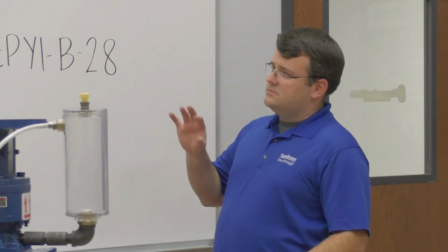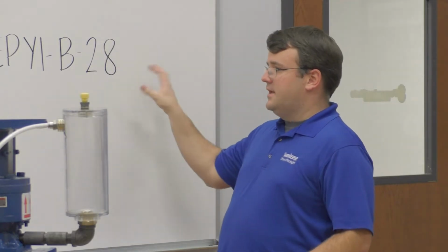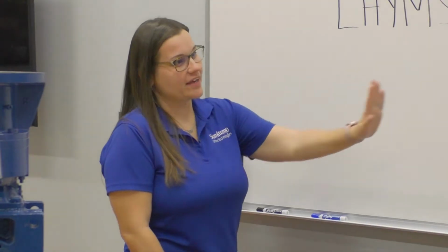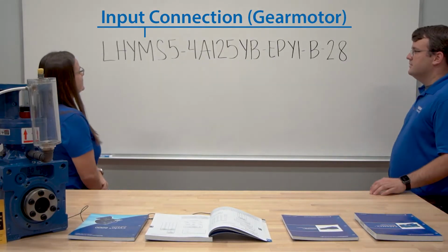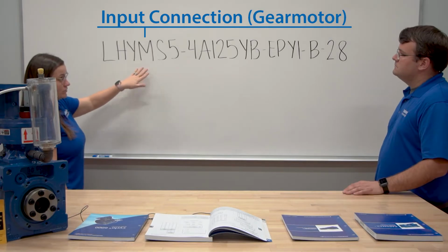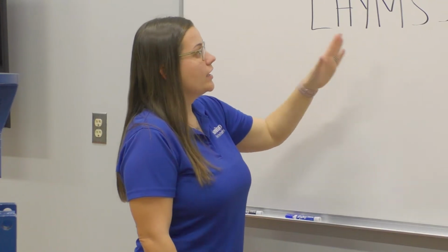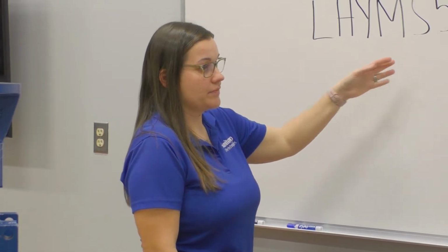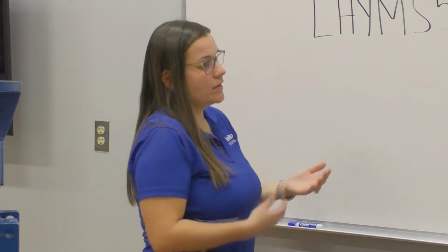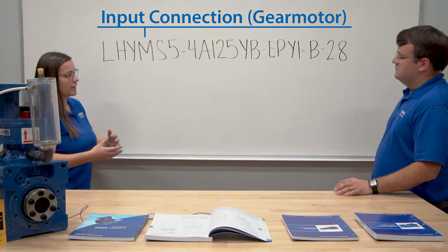Okay, so there's a lot of things, we're going to reference that a lot going down the list here. There's a lot of things that tie into, if there's a motor, some things go away. There are other things cluing us into additional information. So keep that in mind as we go along, but yes, motor is kind of critical there. Yes. So again, this M alone, just the M, tells us that it's an integral motor. If you have a J or an X in front of your M, that's telling you have either J for a C face or X for a quill adapter, and then we supplied a motor. You can also have it with just a J or an X, and we didn't supply a motor at all. It would just be reducer only and ready to be mounted with a motor.